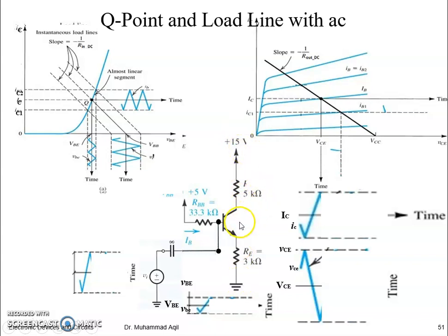It means the increase in IC is possible because of a decrease in resistance between collector and emitter. We have internal resistance, we will discuss it later. So we can say that as well. But now you can see when VBE changes, IC changes in the same direction. VBE increases, IC increases. VBE decreases, IC decreases. And as IC increases, the contribution of voltage across these resistances will increase, and VCE decreases. So VCE has a negative relation with VBE and IC.